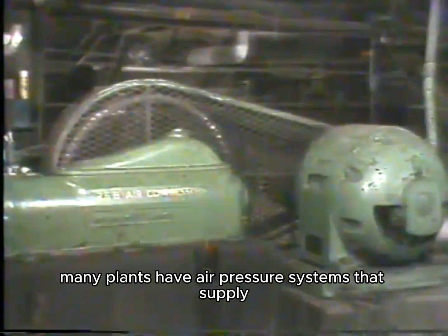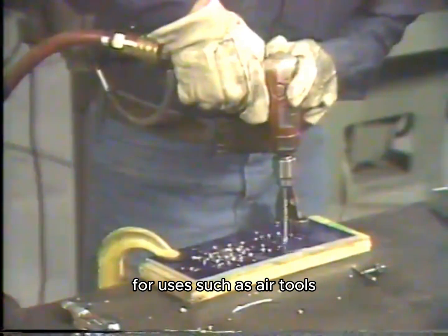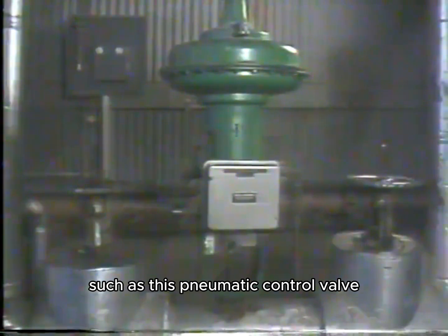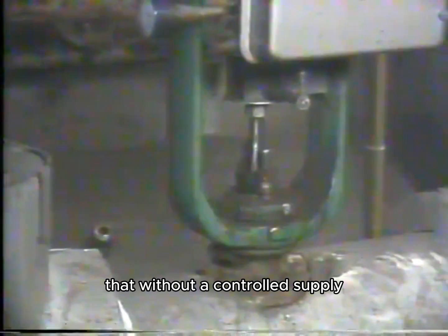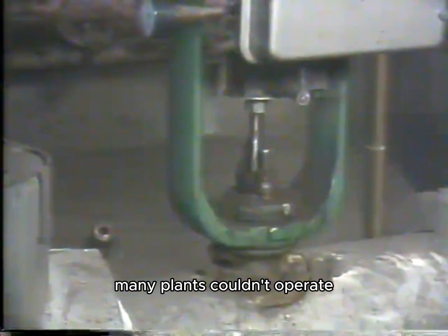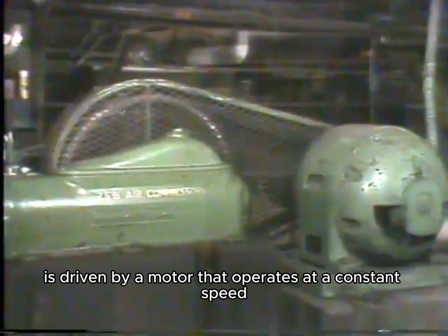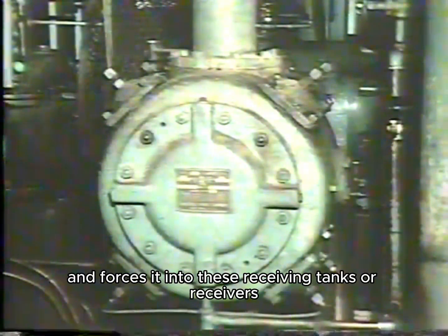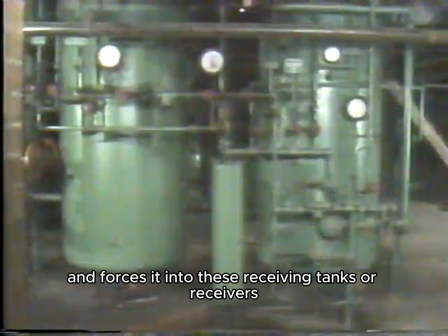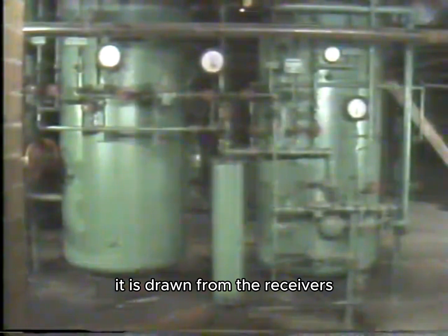Many plants have air pressure systems that supply compressed air throughout the plant for uses such as air tools for drilling or grinding, or pneumatic control instruments such as this pneumatic control valve. So many operations rely on compressed air that without a controlled supply, many plants couldn't operate. The compressor is driven by a motor that operates at a constant speed. The compressor takes air from the atmosphere, compresses it in its cylinders, and forces it into these receiving tanks, or receivers. When air is required in the plant, it is drawn from the receivers.